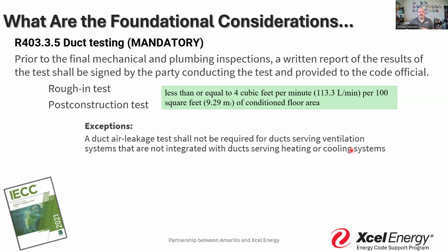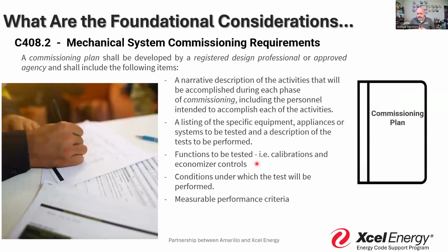That's one of those exceptions that we recognize in the code. So if everything's inside the conditioned space, that's a great reason to know where the envelope is. Then we don't need to test the duct because the loss that we experience will be inside that conditioned space.